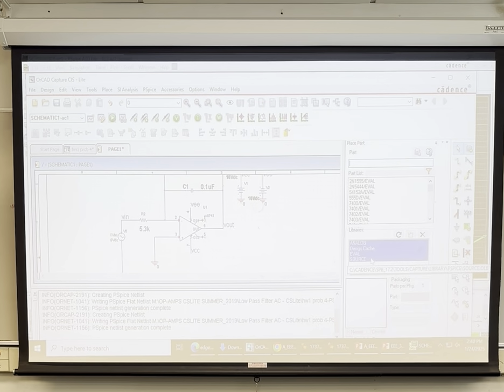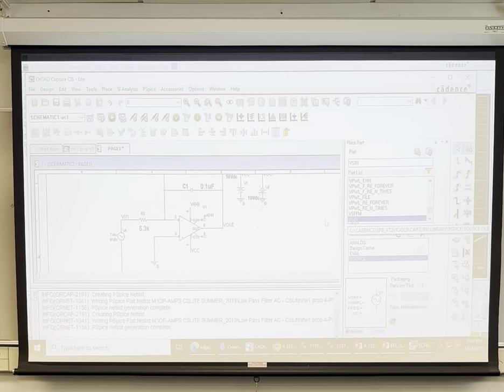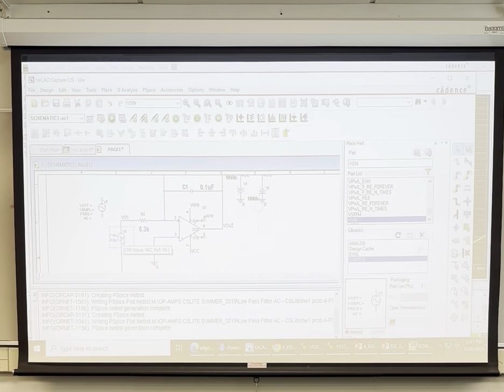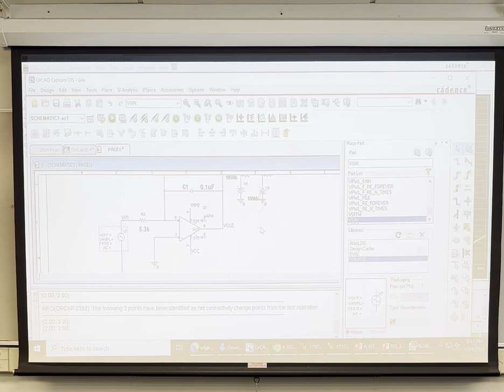and find a V sine generator. So you'll have two schematics, one for AC and one for transient. So this is for the transient. Now, hopefully you're taking some notes here because we're actually pretty much doing a PSpice simulation for your homework problem 3.